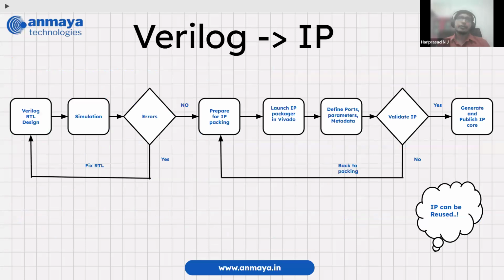So usually when we want to create our own IP, what we usually do is we write a Verilog code, we simulate, you already know that loop, we fix the error and we keep simulating. This is one loop, and then we can prepare an IP packaging. There is a package called Vivado IP package.